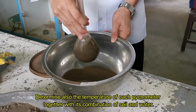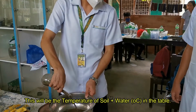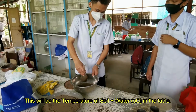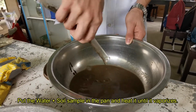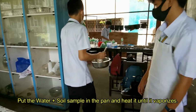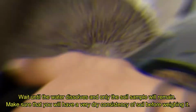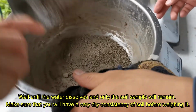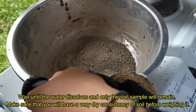Determine also the temperature of each pycnometer together with each combination of soil and water. This will be the temperature of soil plus water in the table. Put the water plus soil sample in the pan and heat it until it vaporizes. Wait until the water evaporates and only the soil sample remains. Make sure that you have a very dry consistency of soil before weighing it.